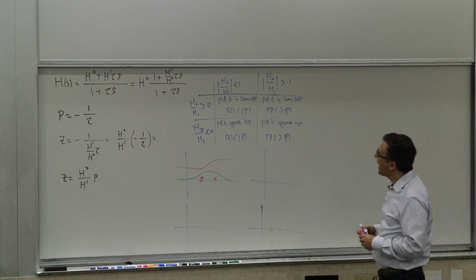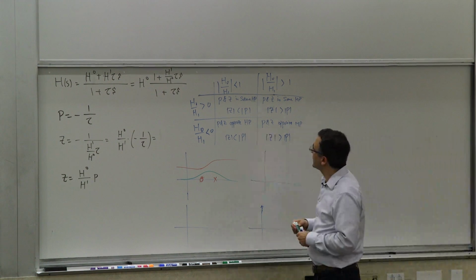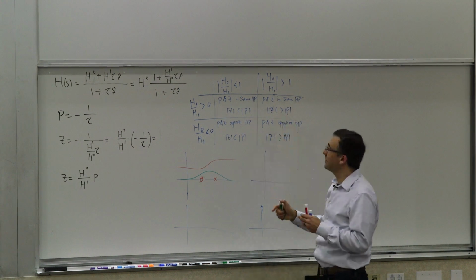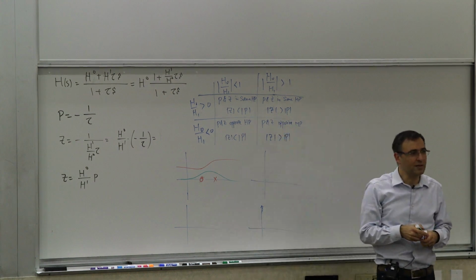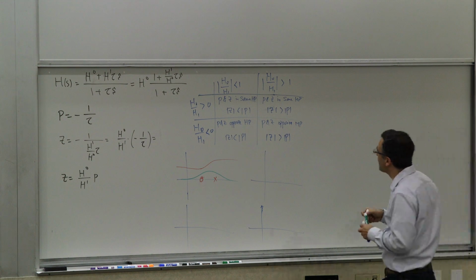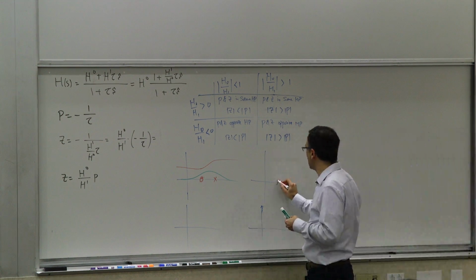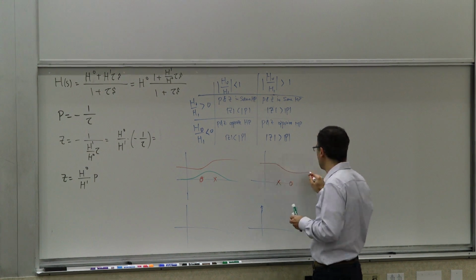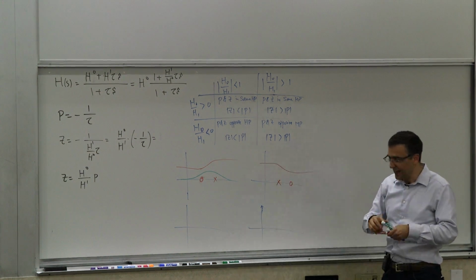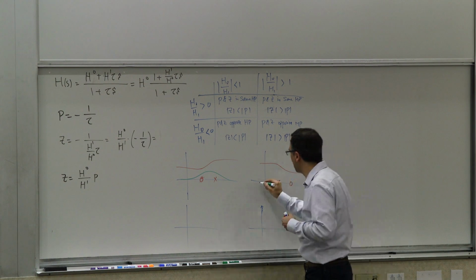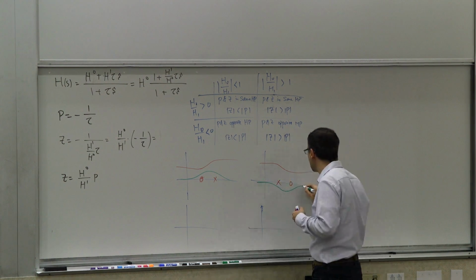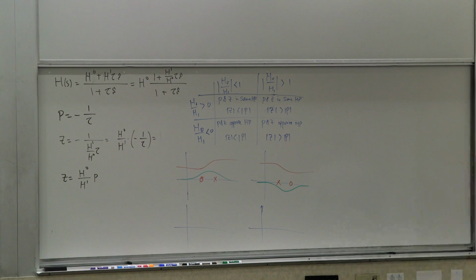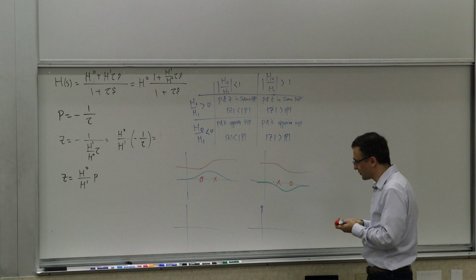Okay. So now the second scenario is that you have the pole. So let's talk about this one. The pole and zero are still both in the left half plane, but one is happening before. Now this time, the pole is happening before the zero. So how would the response look? It would drop in amplitude, and in phase, of course, the phase of the pole hits first, so you go down and you come back up. The green is the phase response, red is the amplitude response.